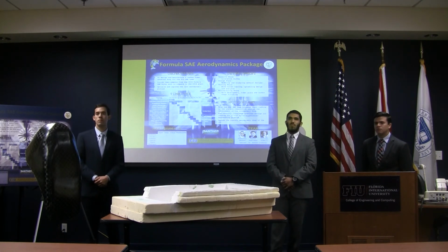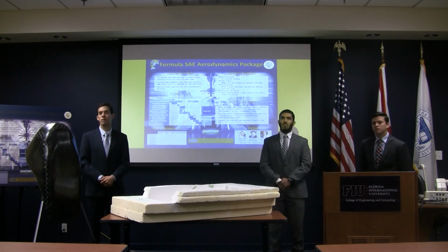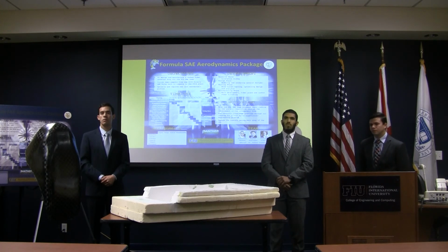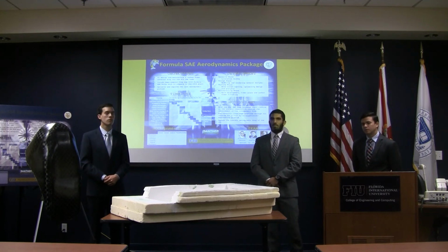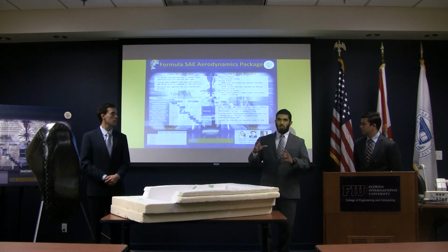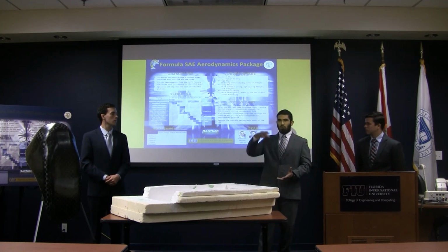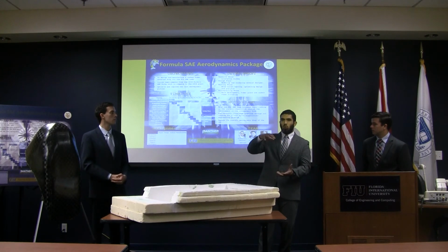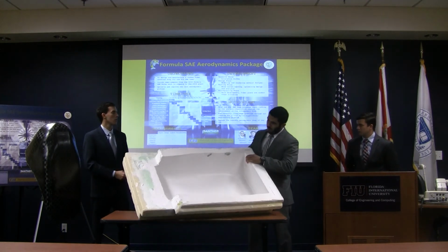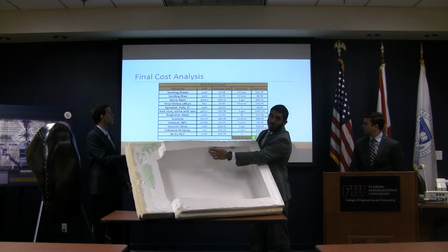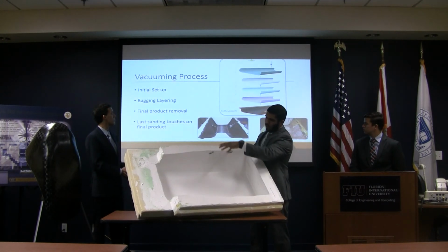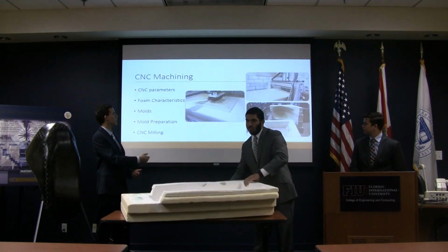Did you ever look at any possibilities? I think you mentioned that the remaining panels required suspensions to be removed and other components to be removed for access. Did you ever look at dividing it around, for example, your suspension plate, making that your dividing line? We did, in fact. The whole front pieces are designed that way. The top and bottom middle pieces are designed to go around the suspension. If you can see in this mold right here, they have cuts for the suspension. This is the bottom part, and the top part would go the same. So we designed for that.